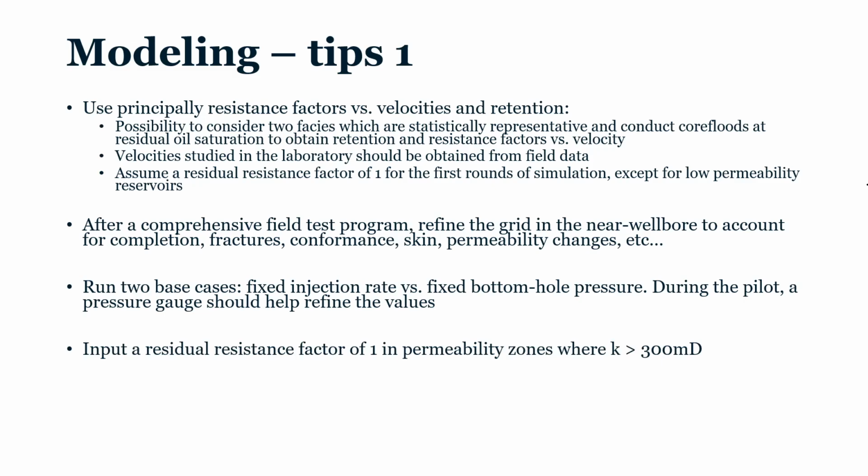You once again need to input RRF, or residual resistance factor, still equal to 1 above 300 mD. Below, you have to measure it. Just don't put any value because you read a value in papers, you have to measure it. It will have an impact on your simulation result.